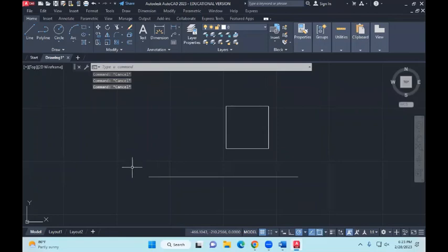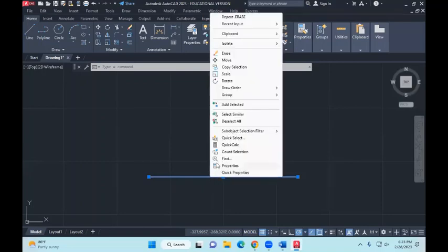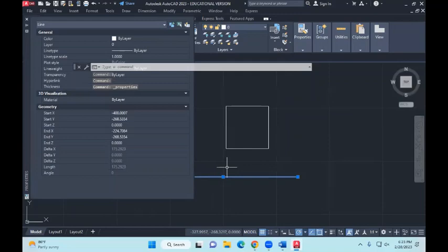So let's change the line weight. You can have any line, or the side of one of the squares you can change. So you take this line, click on it, it's highlighted. What I'd like you to do now for that highlighted line is a right click. First do a left click on the line to highlight it, and then do a right click. A box will pop up. Then click on properties.